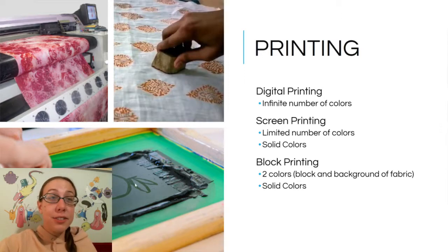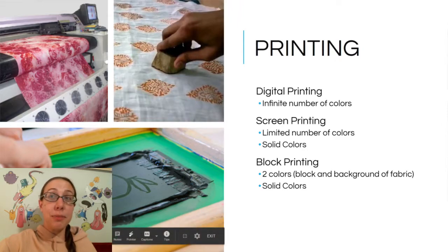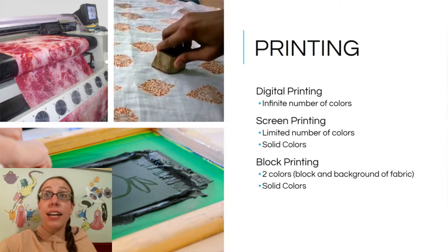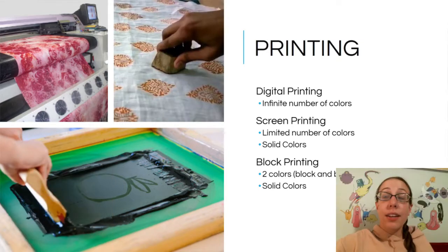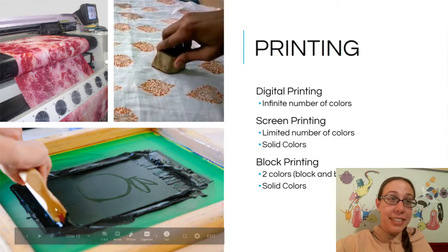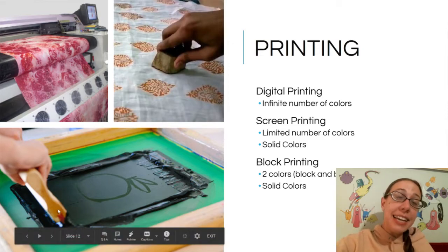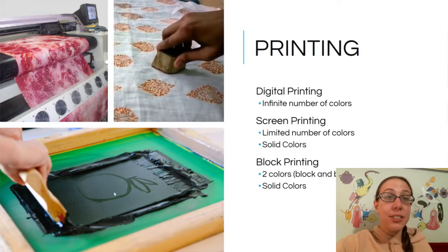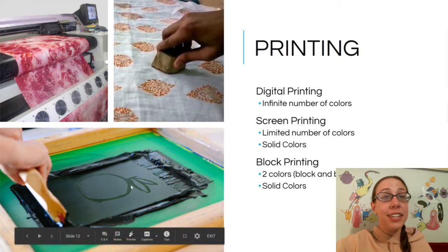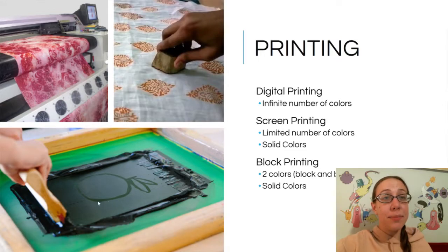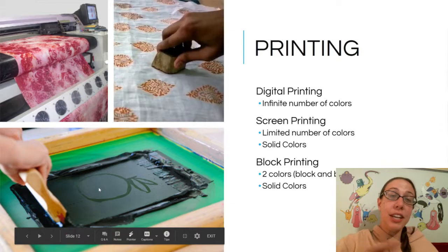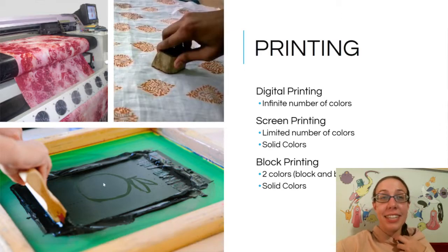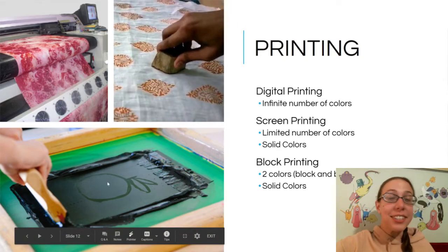In more modern screen printing, but still the traditional screen printing that we think of, we have something called, well, just screen printing. This is for real screen printing because you're squeezing ink through a screen, right? This squeegee is pressing down on a pile of ink and forcing it through the screen, and the screen only lets it through on the area that doesn't have this blocker on it, which has essentially been painted or applied in that pattern. There's various ways of getting it to be perfect.